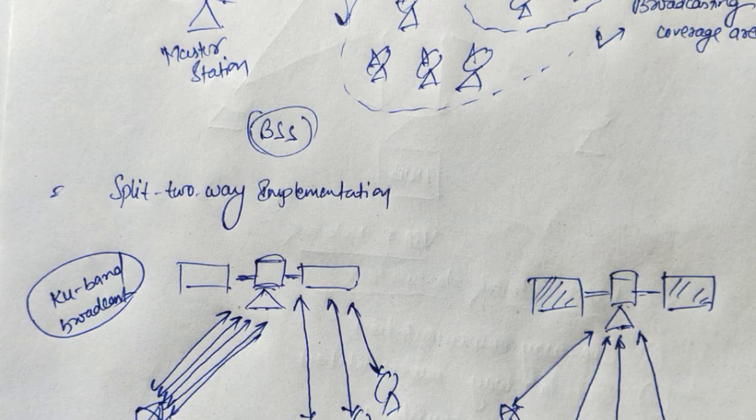The relatively high capacity downlink stream is not complemented by an uplink capability from the user terminal, and if the BSS downlink is used as the download channel from an internet service provider, the only option the user has for a return link is via another telecommunication channel, such as a standard telephone line. The internet protocol, that is IP, is therefore split between a satellite downlink, the outbound channel, and a terrestrial telephone line, the inbound channel.